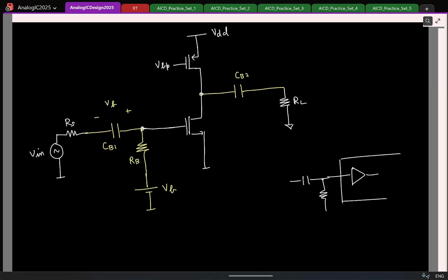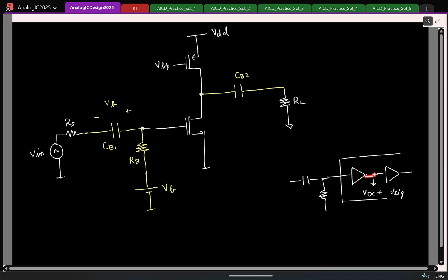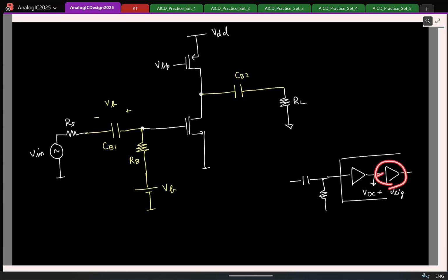And let's say you want to give this to a second stage of analog circuitry. You once again don't do this. You try to directly connect it. And remember, the output here will have a DC part and a signal part. You design the circuit so that the DC at the output of the first stage is compatible at the input of my second stage, so that you can avoid decoupling the DC, adding a different DC and stuff. But of course off chip you have to do something like this to couple the signal.